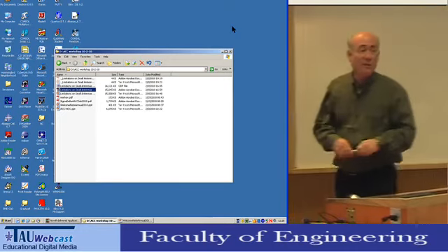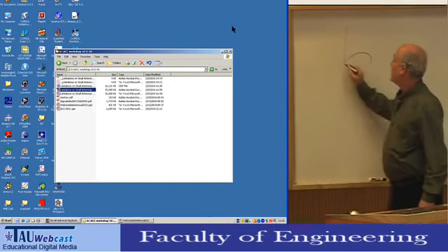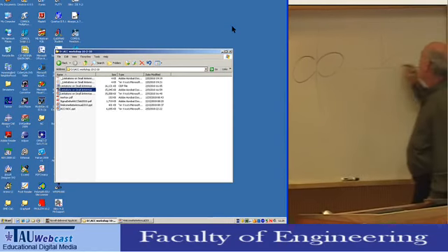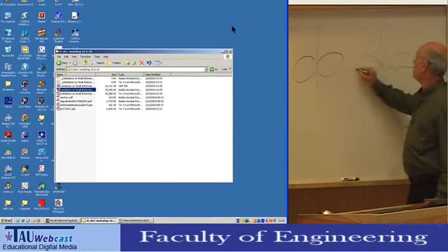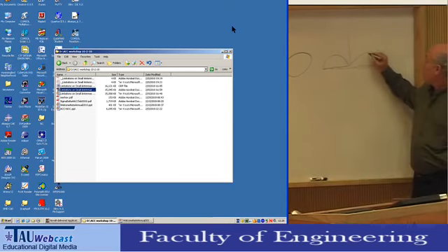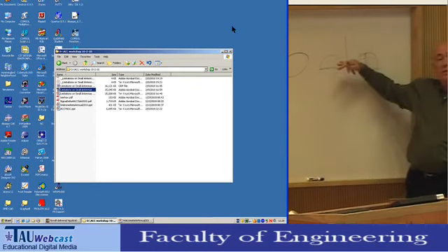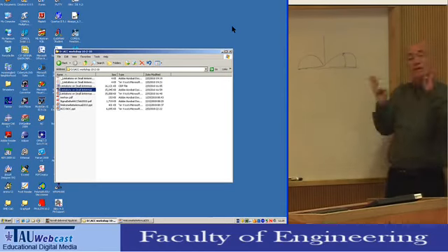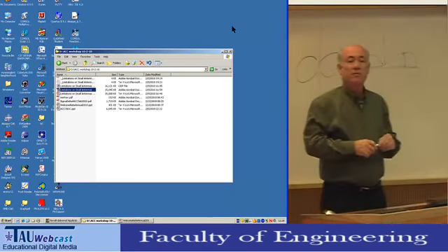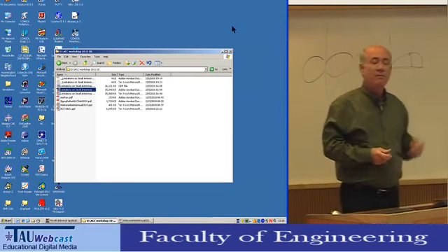Let me try to explain it very briefly. Here's the dipole, and this is the radiation pattern, more or less. Here's the monopole, and this is the radiation pattern. See the difference? There's nothing here. So you have a narrower beam here. The field distribution is the same, but it's chopped in half. The beam is narrower. Obviously, the aperture is larger. Yeah, it's a textbook. It's actually an exam problem.